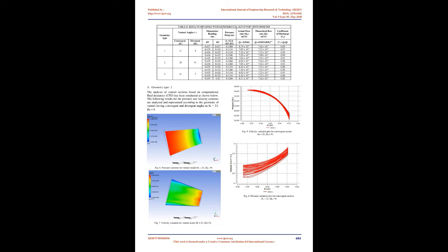throat diameter, D. The pipe diameters for a given Venturi model kept 40 mm for both inlet and outlet section. The throat portion is 24 mm in given models for Venturi design. The total length of Venturi including convergent and divergent is 135 mm. Here, ANSYS Workbench 14.0 is utilized for the computational fluid dynamics, CFD, approach.